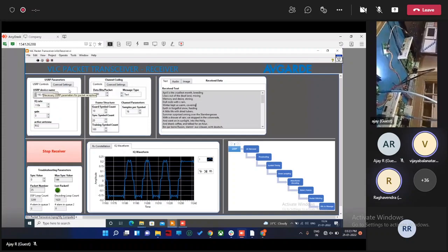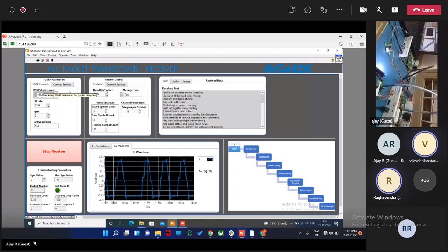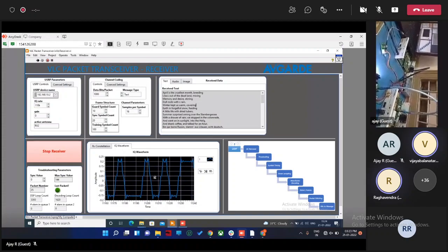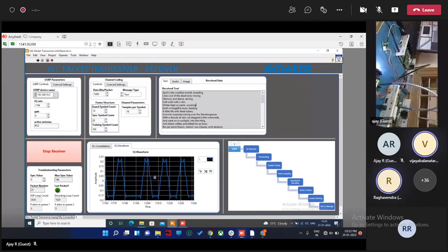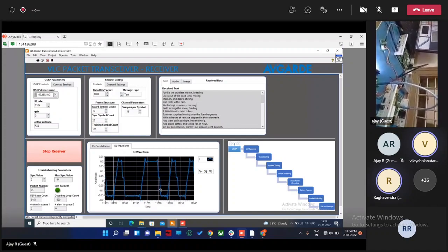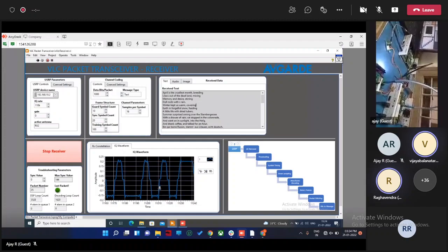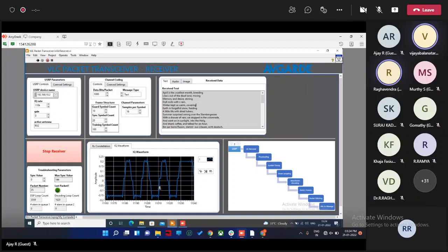Right. So as you can see, the waveform that's present over here doesn't look like a proper Manchester waveform where you have a little bit of ups and downs. This is simply because of, one, it could be channel effects. And second thing, when the voltage in a circuit goes from 0 to high, there is a small amount of extra increase that happens in the current. So that could be the cause for those small spikes that you see. But again, the spikes are very small, so you won't be able to recognize or realize that there is an error. At least in the code, the thresholding happens at the 0 point. So those small errors shouldn't cause us any issues at all. As you can see, we're able to receive the text properly without any issues.